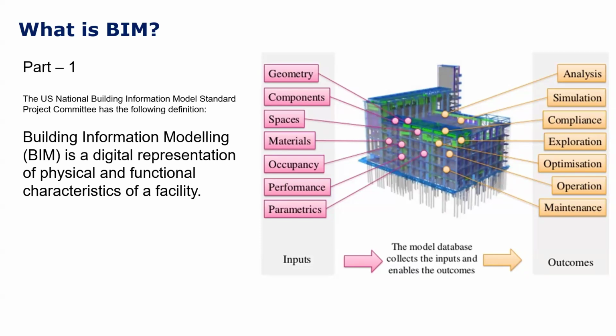So Revit works on categories, which are further divided into subcategories depending on the types of elements. If I have to tag those elements accordingly, I would go with the type properties. Coming back to spaces and materials, you can input n number of things. For example, if I take gypsum board, it would have certain thermal properties embedded into it. Even if I don't know, if I have a certain specification of a material given to me, I can input that into Revit for developing the schedules out of it.